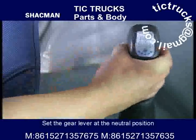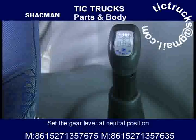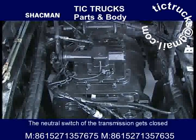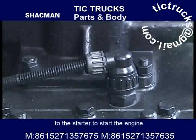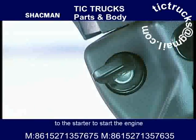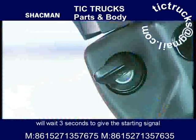Set the gear lever at the neutral position. The neutral switch of the transmission gets closed. The electronic control unit supplies power to the starter to start the engine. Or the electronic control unit will wait 3 seconds to give the starting signal.